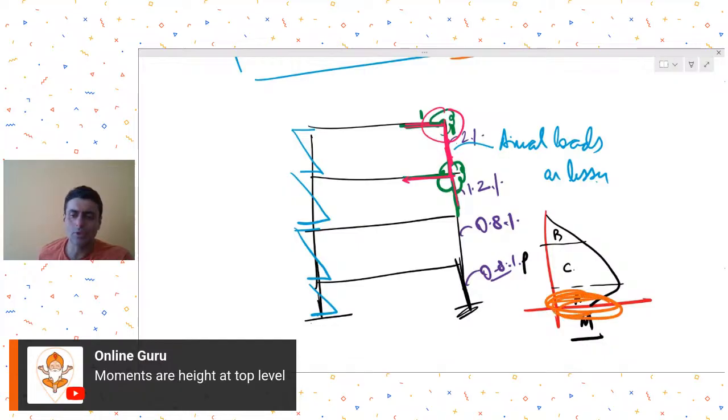When you are in this zone, you can see that the capacity curve, or the capacity of your column, is lower. Because the design capacity of your column under P and M interaction is lower, you have to provide more reinforcements.